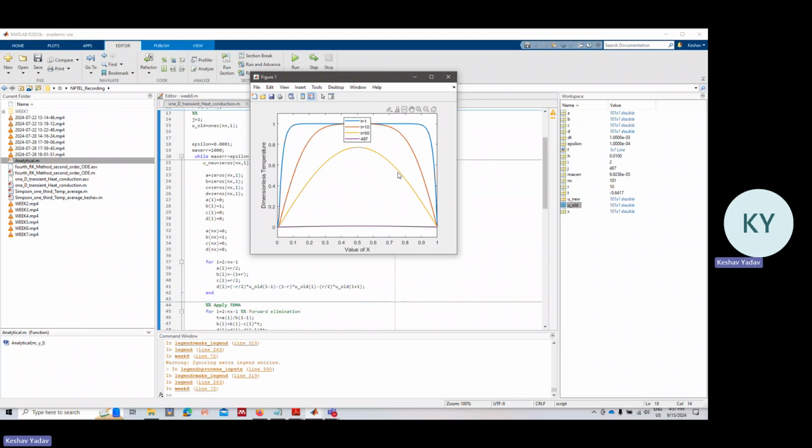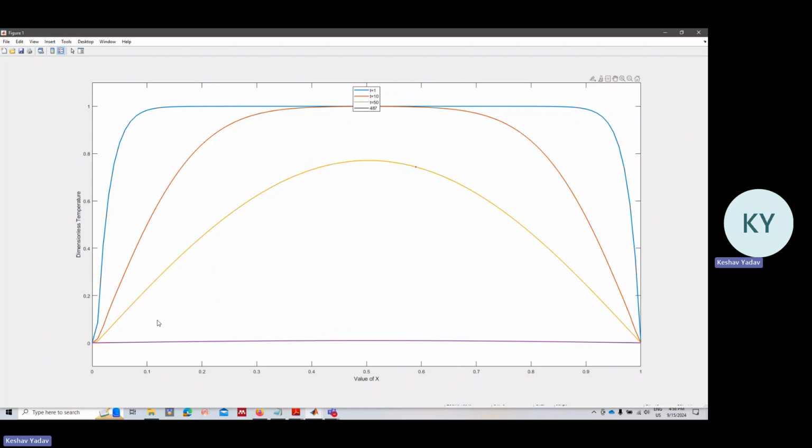Okay. Now what you need to do is plot the analytical solution also on this point. Rather than plotting it as a continuous line, plot this numerical result as a scatter plot, and plot the line plot as the analytical solution. Okay. And you see whether it is matching or not with the actual result. Okay. I hope this is clear now.